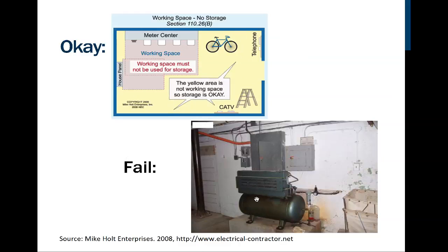Now this air compressor, on the other hand, I don't know if you can tell here, but this panel extends below the bottom of this air compressor. You can't even get the door open all the way. Definitely a fail.